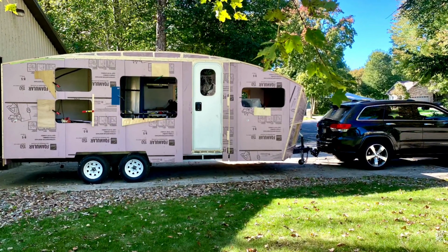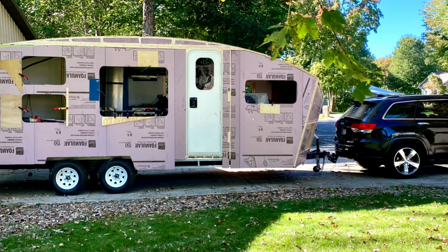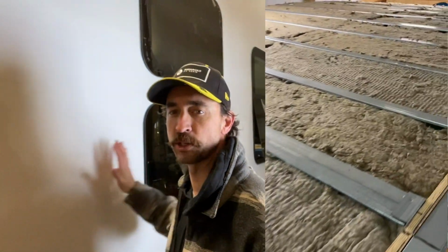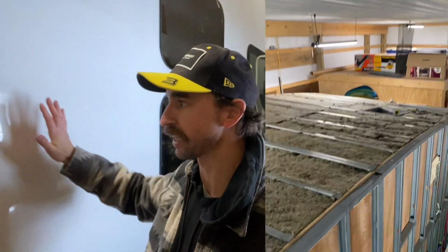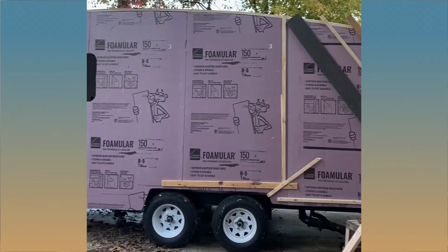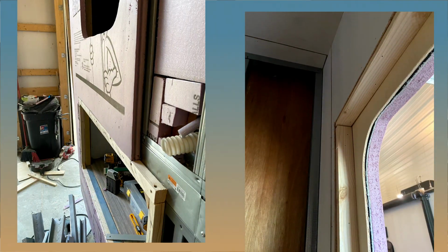So I really focused in on that R value with things like rock wool insulation on the floor and ceiling and the rear wall. And then XPS Foamular, Owens Corning Foamular on the outside, skinning the whole thing to give it a really, really tight, well-insulated box. Had to do some research on some construction detail work there and borrowed a lot of stuff from the more recent barn-dominium construction movement as far as how I did around my doors and windows and corners and baggage doors and all that stuff. Was a lot of stuff to figure out, but we're getting there.